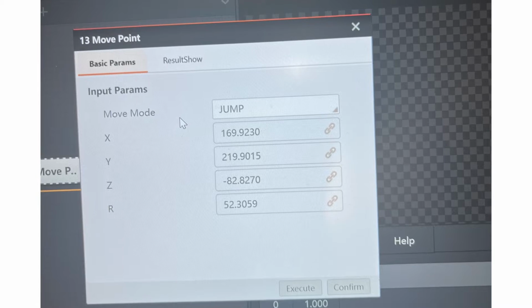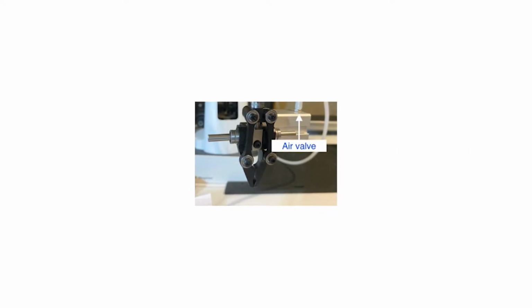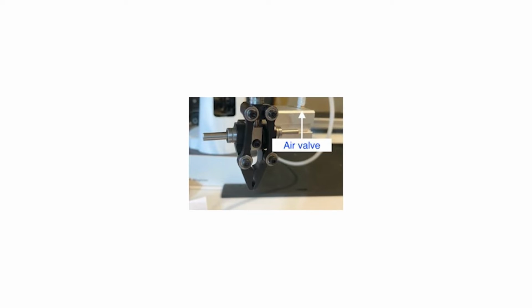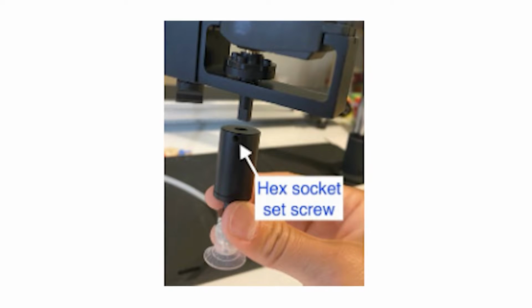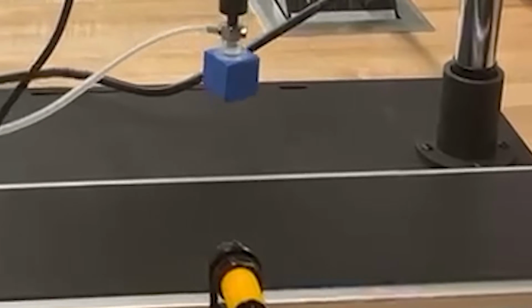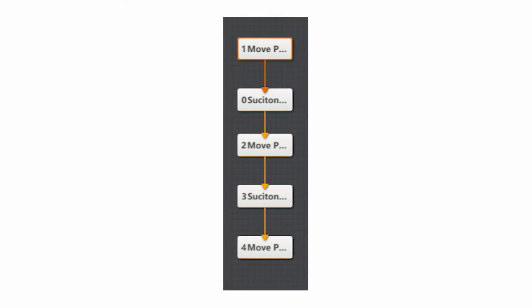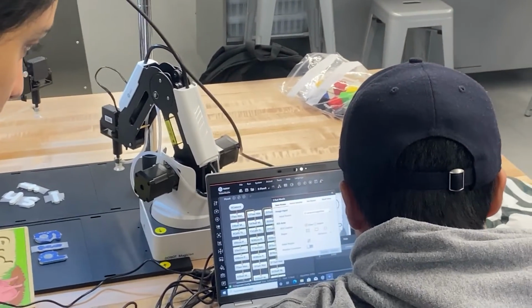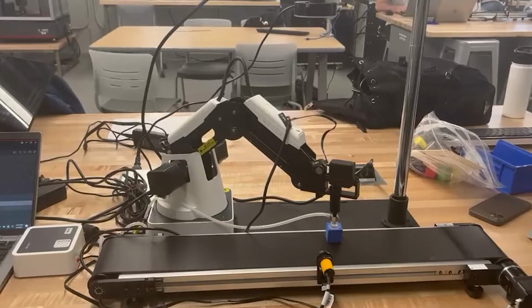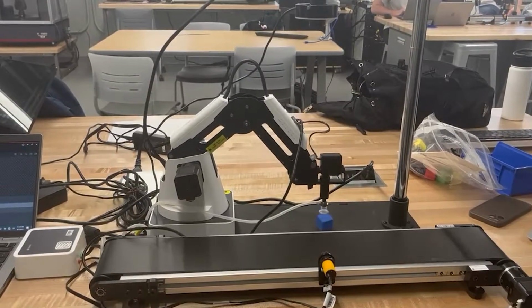Following the exploration of the robot's basic movements, the team looked to see how the Dobot could utilize different end effectors for different tasks. We first explored the use of the suction cup end effector, which utilizes suction to pick up objects. The code would have to dictate when the robot begins suction to first pick up an object, and then the code would have to dictate when to disengage the suction to drop an object. The team explored the suction end effector by picking up a block and then dropping it in another location.